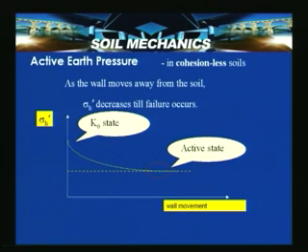But otherwise, when it is a cantilever wall or a cantilever sheet pile wall retaining the soil, they have to be designed for the active state when they are subjected to movement for attaining this active state. From the next slide we can see that a minimum movement is sufficient to reach that active state. So it is seldom possible to maintain K naught conditions, and it is not wise to have such a conservative design. So it is designed for the active state only.